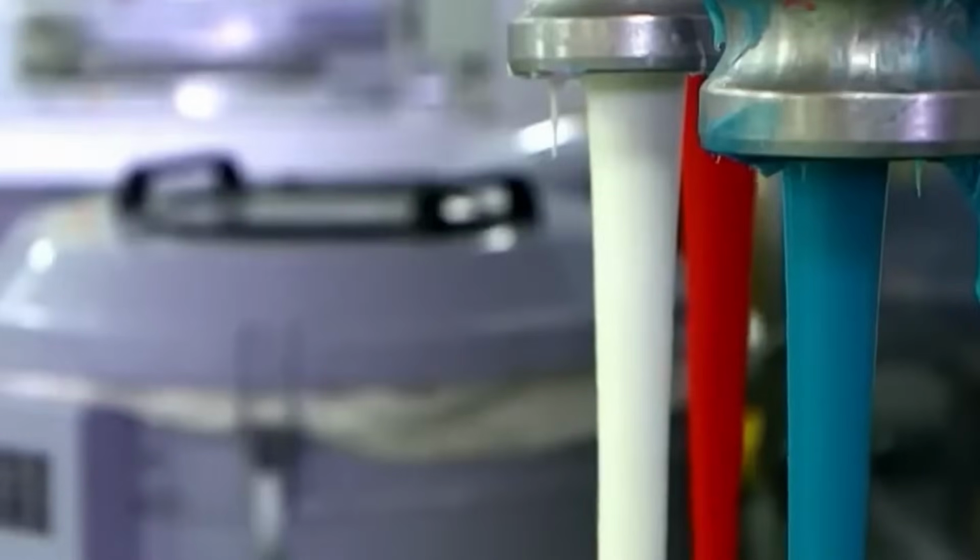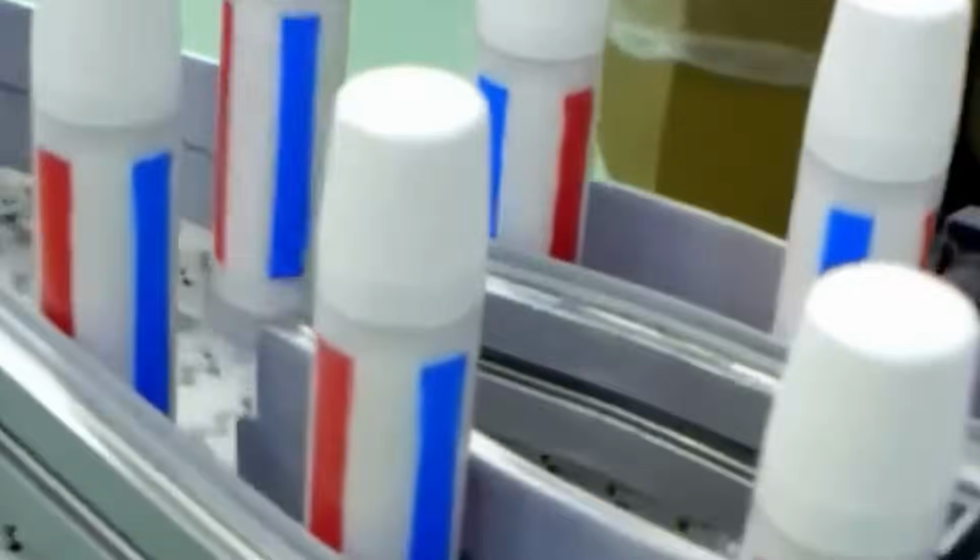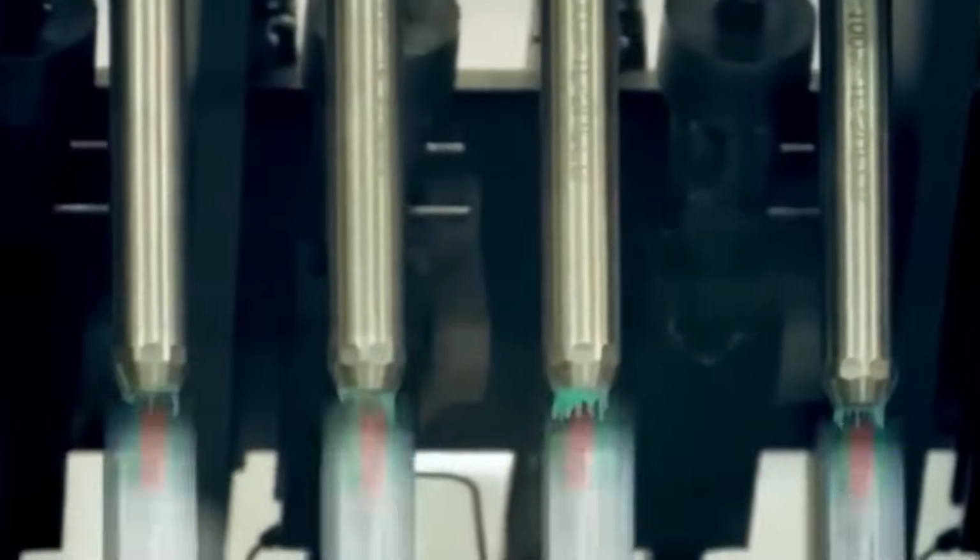Colorants such as titanium dioxide or FD&C dyes are added as aqueous slurries or predispersed concentrates. These are introduced late in the mix cycle for visual uniformity. Color matching is performed using spectrophotometric sensors positioned above the mixing vessel.